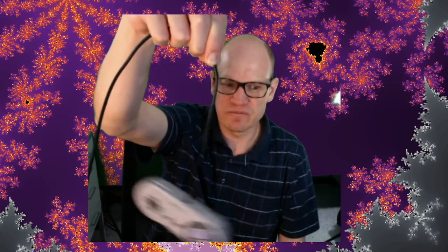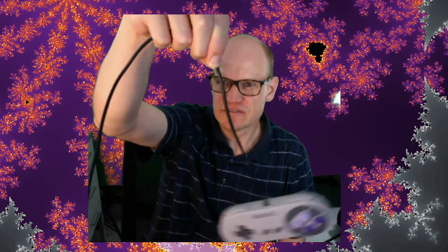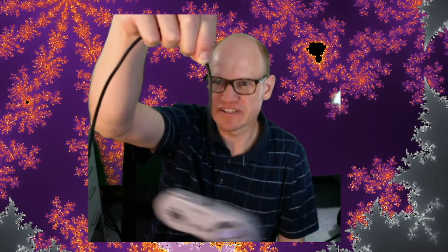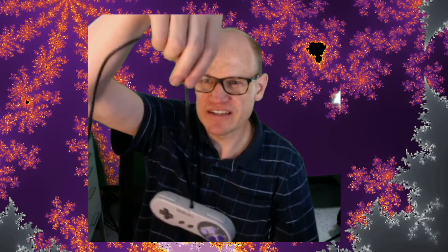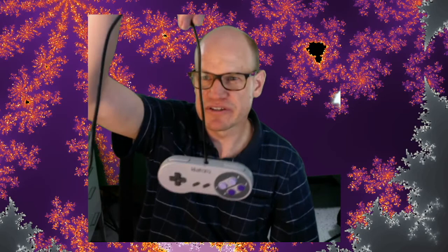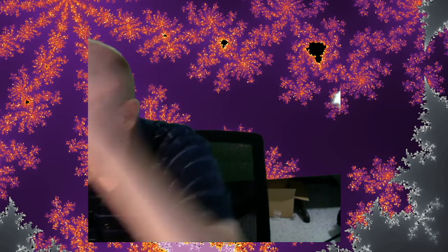Now, I can have it oscillating so that even a small, so here you can see that my hand is not moving very much, but the pendulum is moving a lot. So that means that the response would be very large. This is not a ratio of 1-to-1. This would be a ratio of like 10 or 15-to-1, something like that. Now, if I wiggle the top very, very fast, then you'll see that the pendulum is not moving very much at all. I wiggle it very fast, and the pendulum actually is just kind of sitting there. There's hardly any movement of the pendulum. The same thing is going on here.